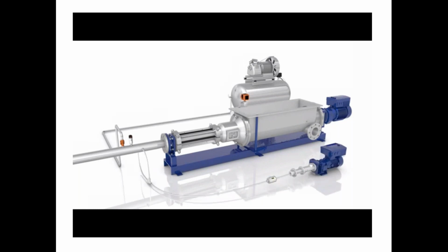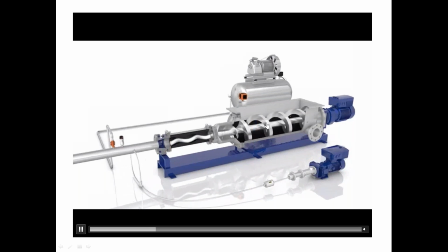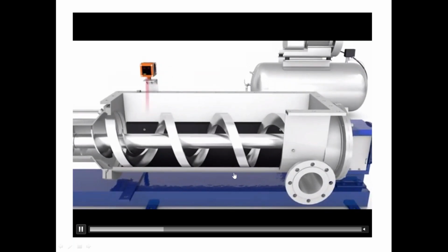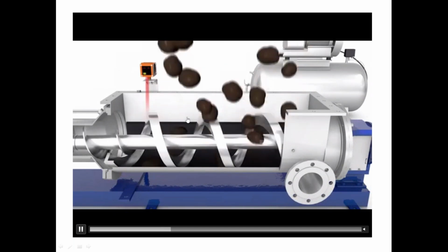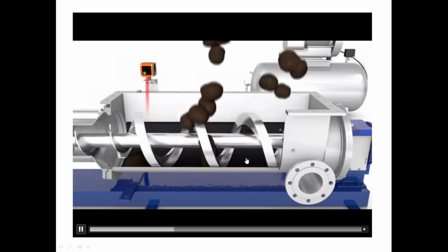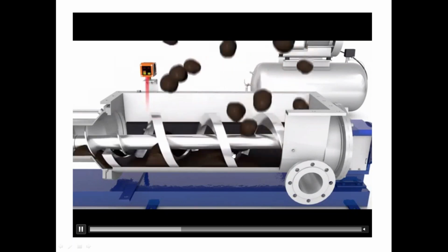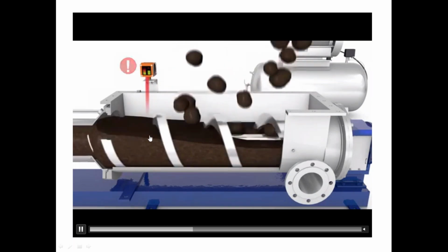We have a compressor for air injection, a ribbon auger, and a small polymer injection pump. So as the cake enters the pump, the ribbon auger conveys this to the rotor and stator compression. It also cleans the bottom of the hopper. This laser will tell the pump when to speed up or slow down based on the level in the hopper.